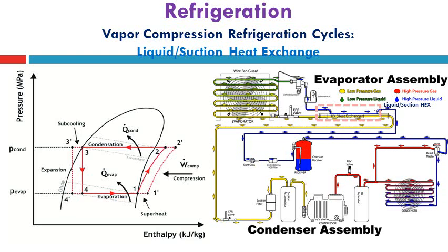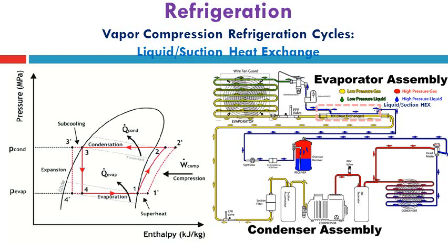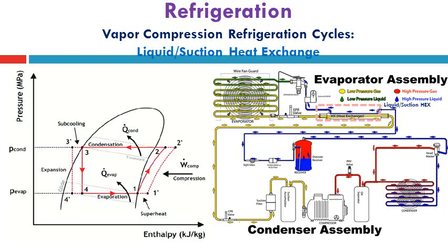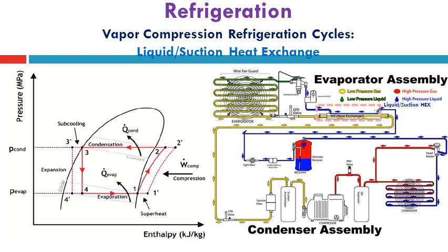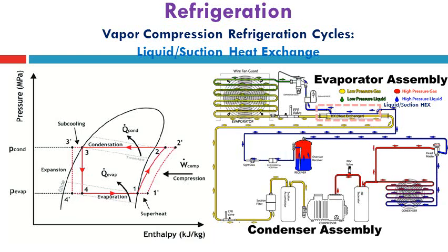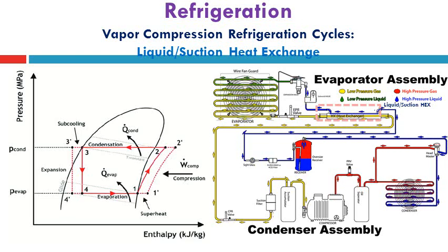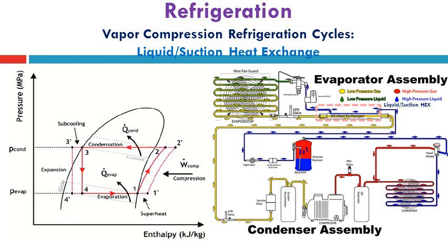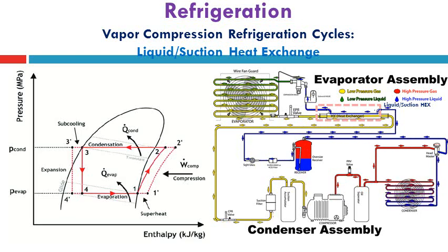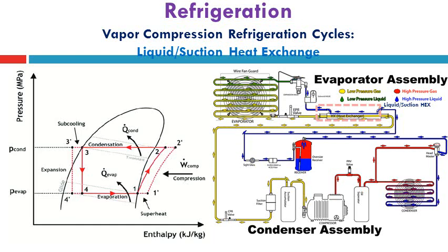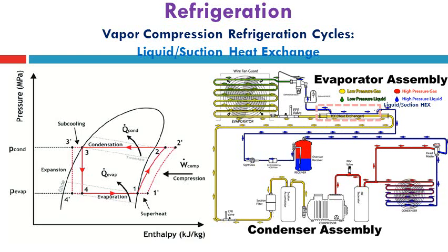Also the pH diagram is still here to present the effect of superheating and subcooling between the suction line before entering the compressor after going through the evaporator, and the liquid line just before entering the expansion device at high pressure and high temperature, so that will allow the heat to be exchanged or transferred from the condensation temperature after this subcooling temperature to the lower temperature.